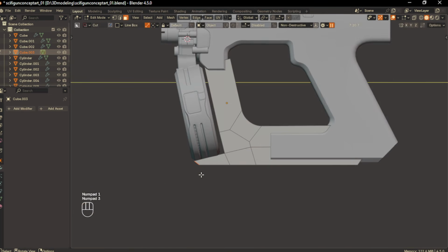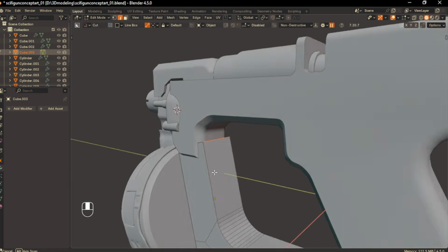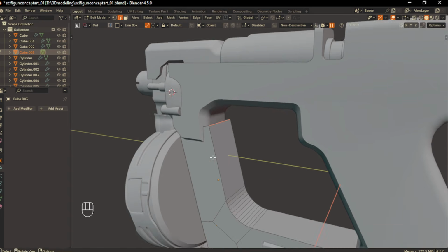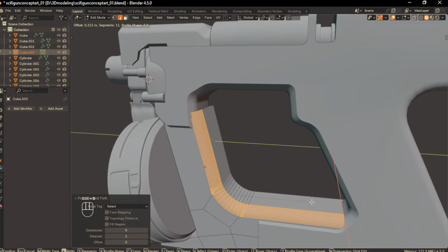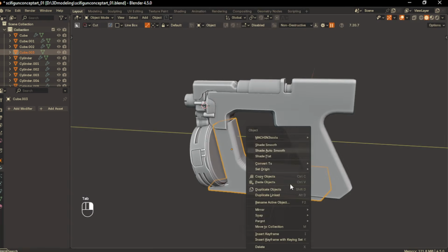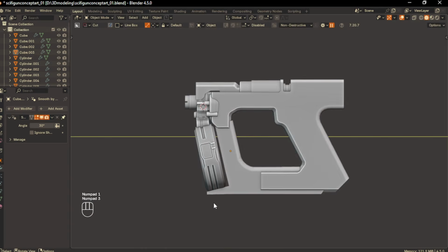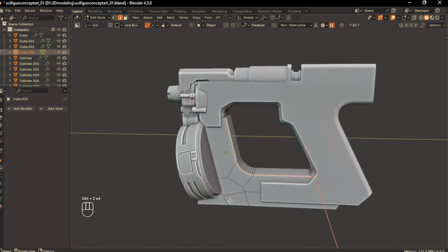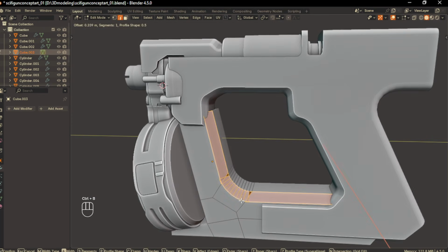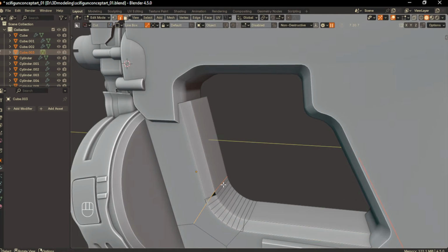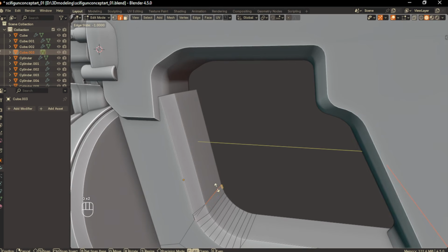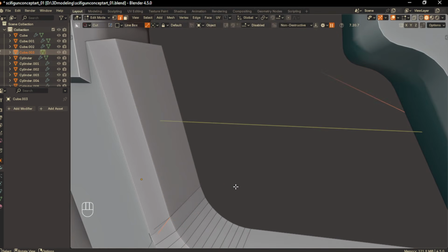This front face, I'm gonna straighten it along the Y-axis. Still feels a bit flat and boring, so I'll add some curve. I'll grab these side edges and add a fillet. Not sure. Let me just try a chamfer instead. Yeah, chamfer actually looks better here, but we got some issues. The vertices are collapsing. Okay, let me just slide it to see if it fixes that issue.